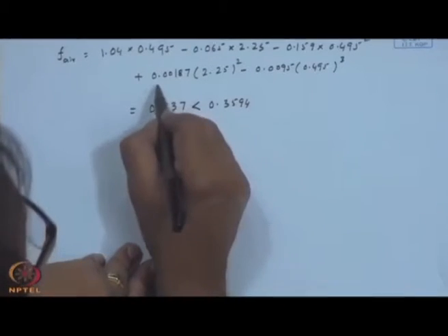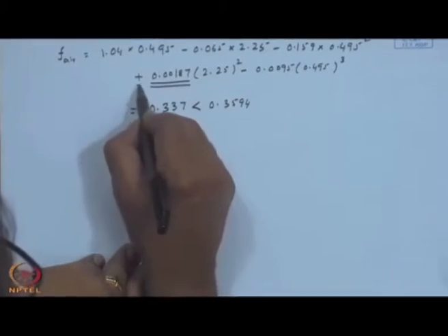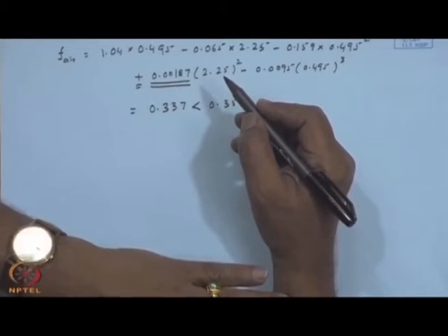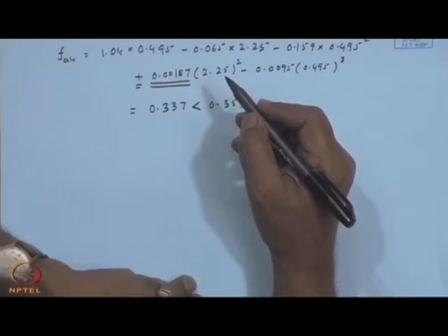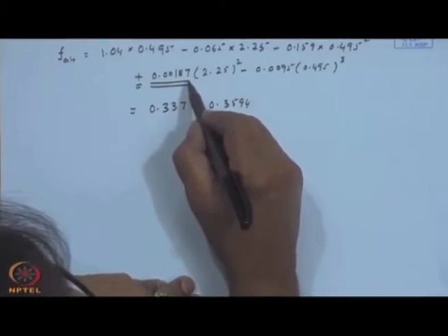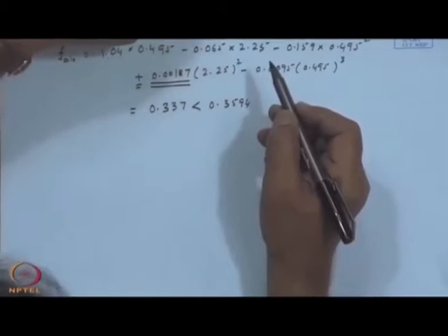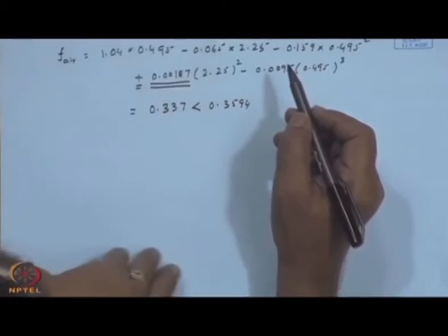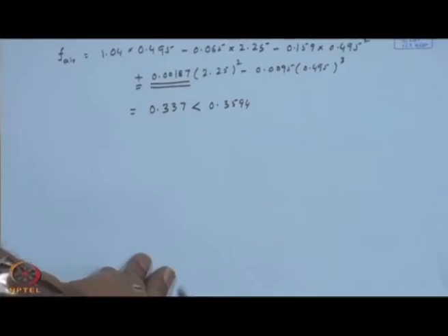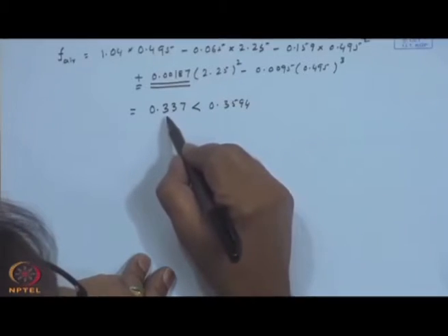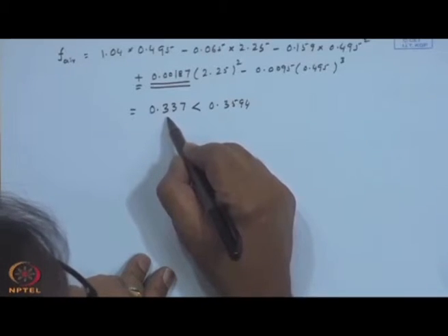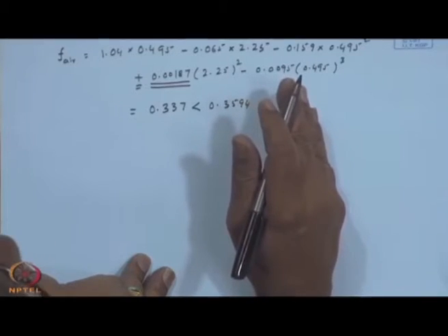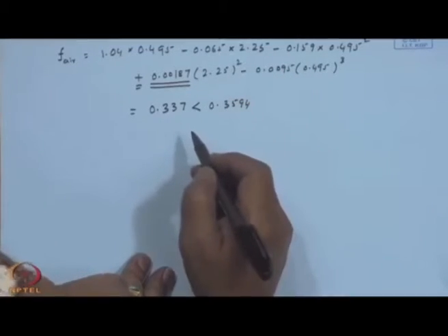So, this is actually attributed to this term with a plus sign, and X c has increased when the flow rate is doubled relative to the standard flow rate. One reason could be, people attribute that at a higher flow rate the storage is very much disturbed. So stratification is not maintained, consequently the effective temperature goes down, making the effective solar load fraction lower than what it would be at the standard flow rate. So, standard flow rate is sort of an optimum flow rate also, right.